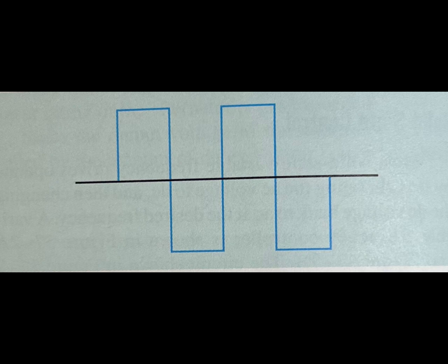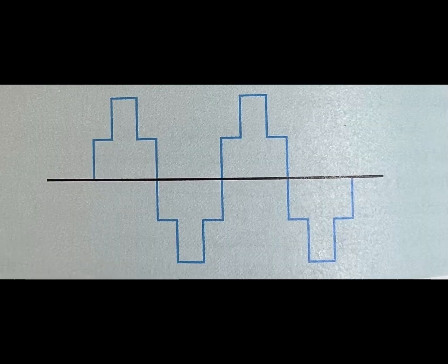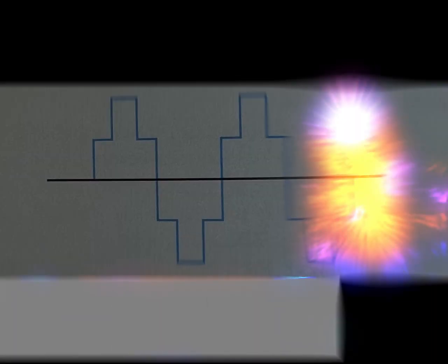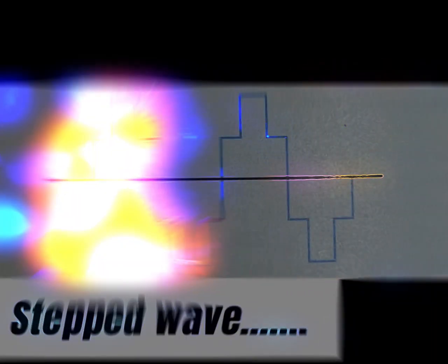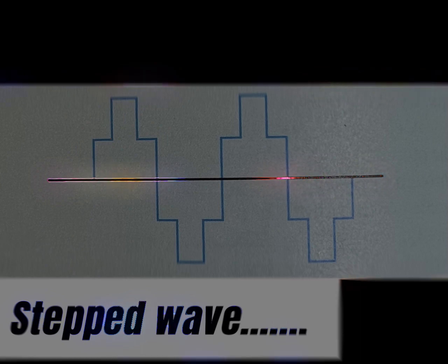For example, assume that transistors Q1 and Q4 are switched on at the same time. This allows T1 to be positive at the same time T2 is negative. If conventional current flow is assumed, current will flow through transistor Q1 to T1, from T1 through the motor winding to T2, and then through transistor Q4 to negative.